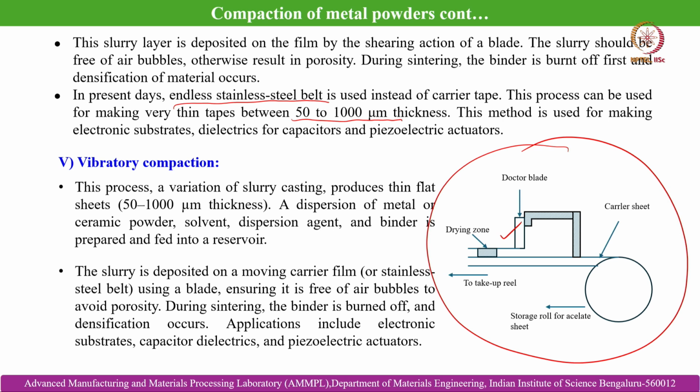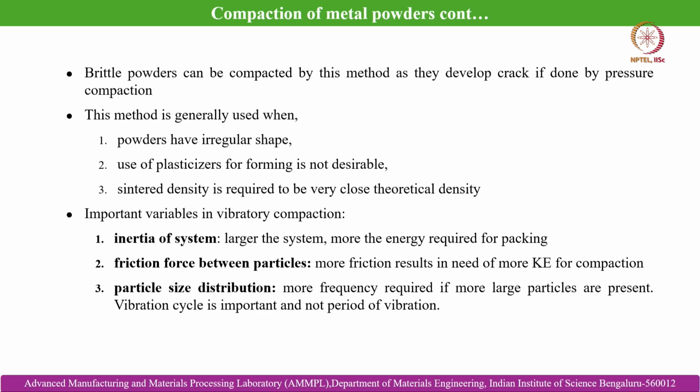So, a dispersion of metal or ceramic powder, solvent, dispersion agent and binder is prepared and fed into a reservoir, similar to doctor's blade casting. So, it is quite the same. Then comes the compaction of metal powder. Brittle powders can be compacted by this method, as they develop cracks if done by pressure compaction.